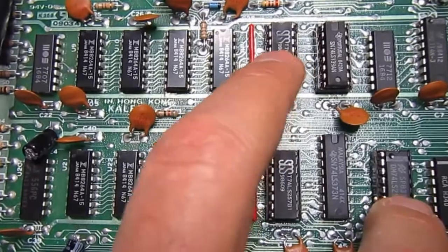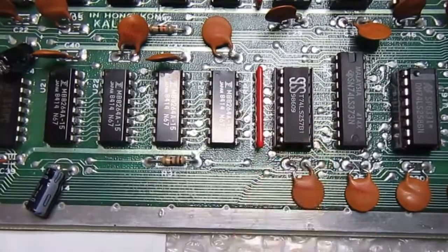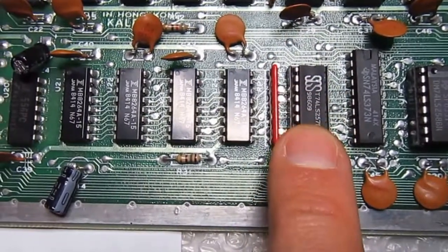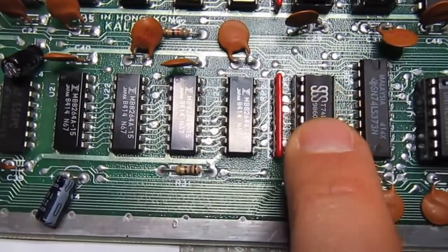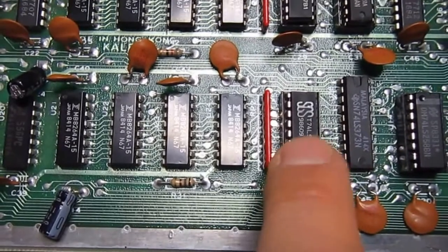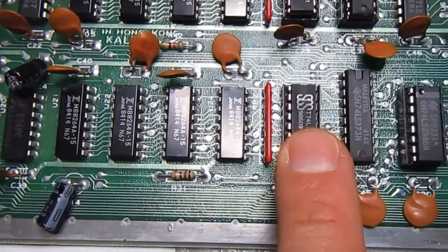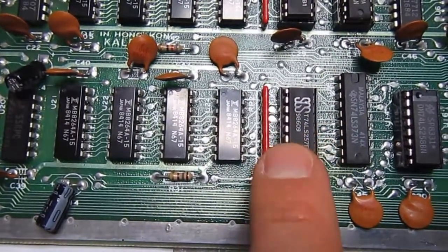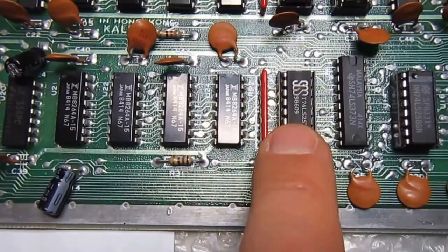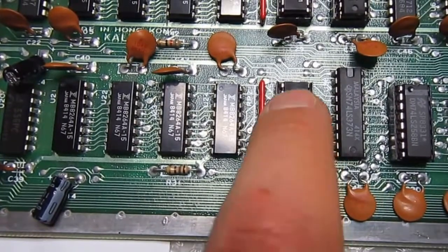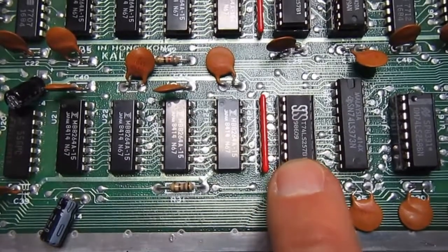Then we still had a blank screen, and going with the oscilloscope on the output of this one, U25, which is the twin of U13, I discovered that also this one was bad, because one output was not going to the full logic levels, so I changed also this one, but still a blank screen.